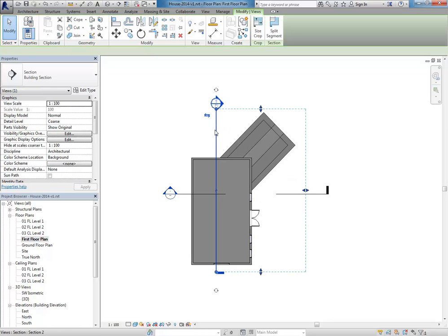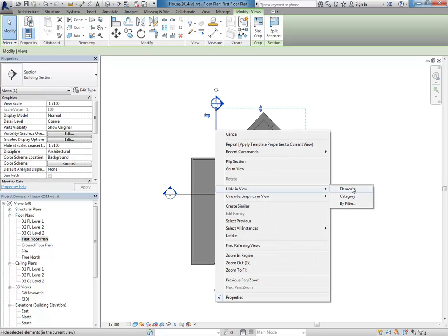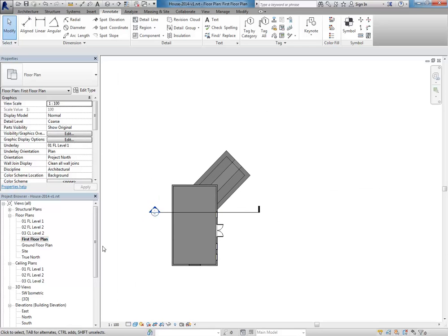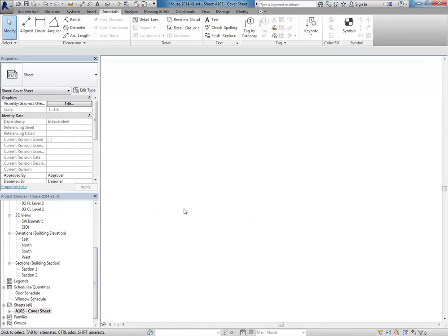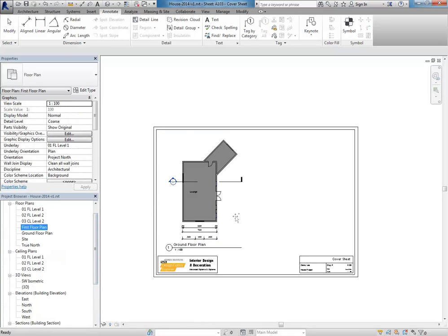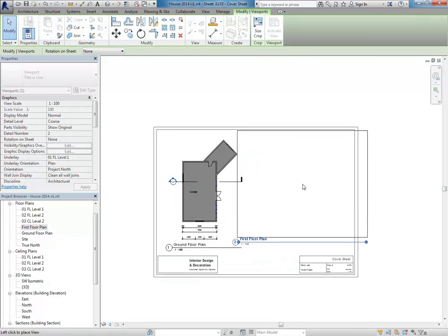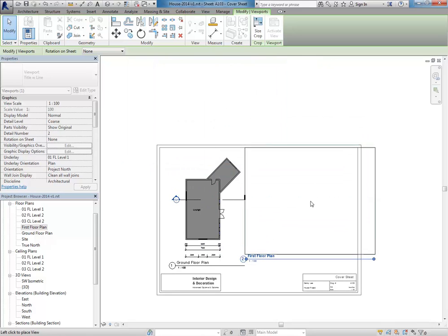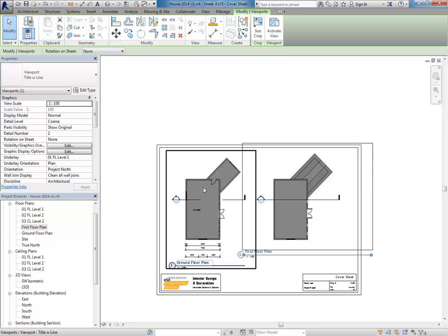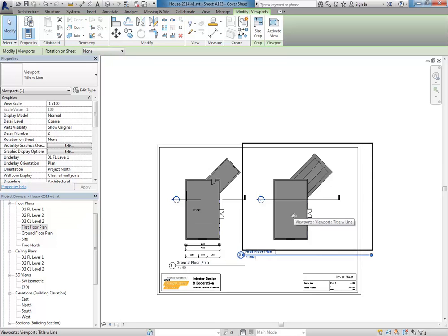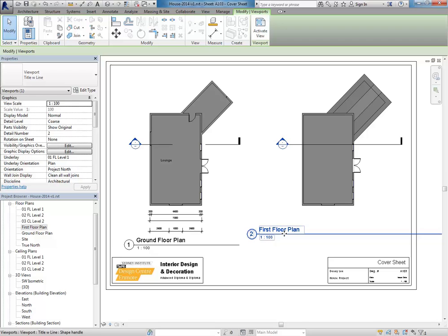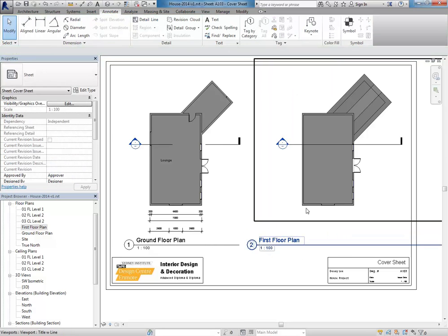I've got to change some things individually because obviously they were hidden manually, but otherwise most of the work's done. The cropping I might need to check, but that's okay. And so that can now just go straight onto the sheet. And so when you move the cursor there, you'll see if the view can line up, if it makes sense to line it up. So in this case, it would make sense to have it projected across so these walls align. It should give you a projection line to do that. So yeah, and again, you'll get those when you drag things like the tags to line those things up.